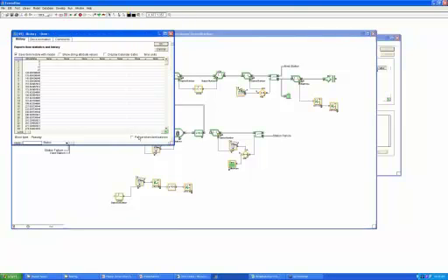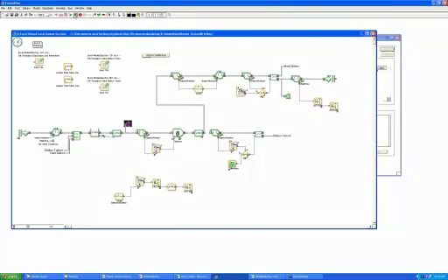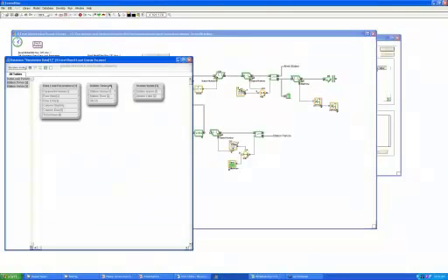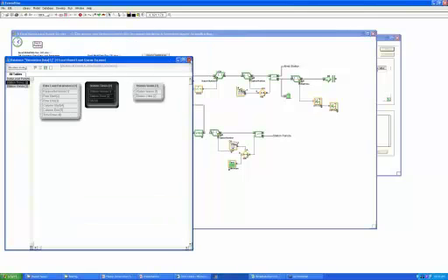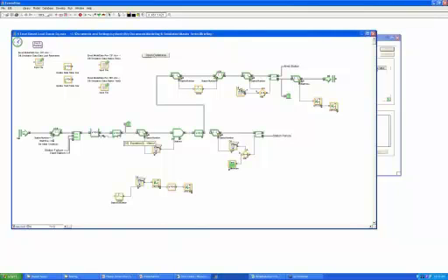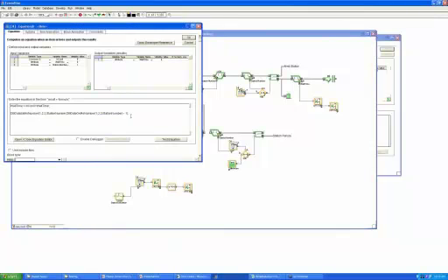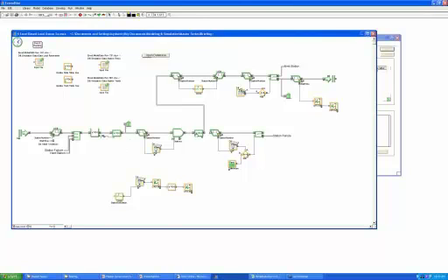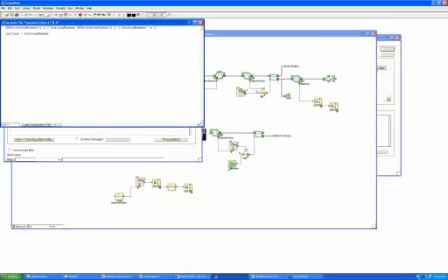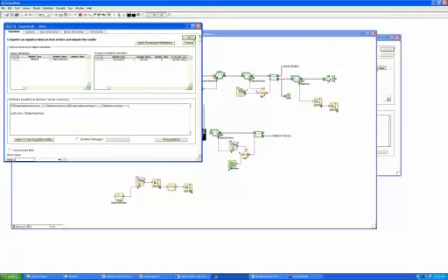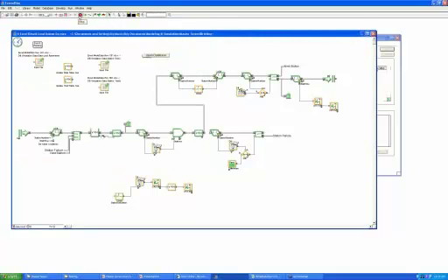I'm going to pause the simulation when the first item passes. And we'll notice that when the simulation pauses, the station quantity has dropped to 0. And this is done in this equation, which subtracts the number of stations from the current number of stations. Subsequently, when it's done processing, the same equation then adds the station back into being able to be used. Let's stop this model.